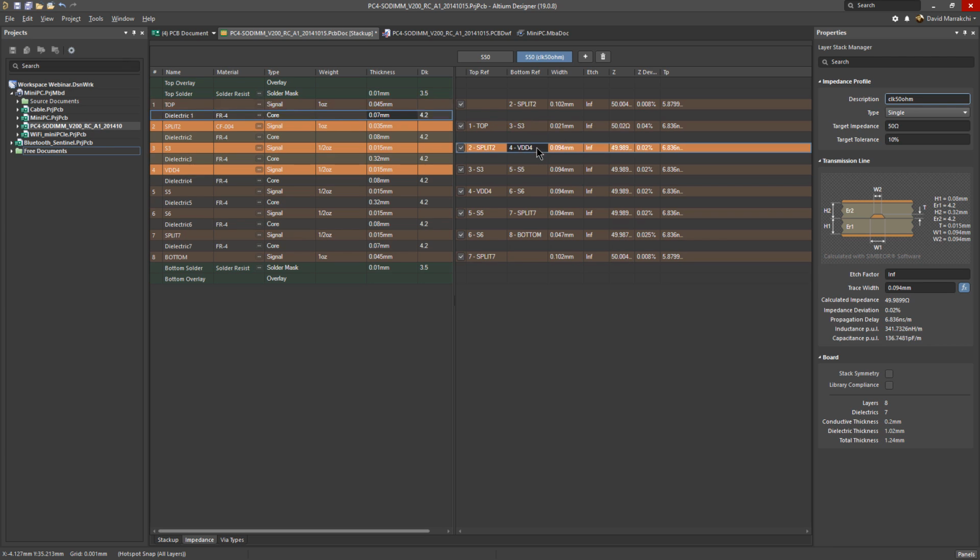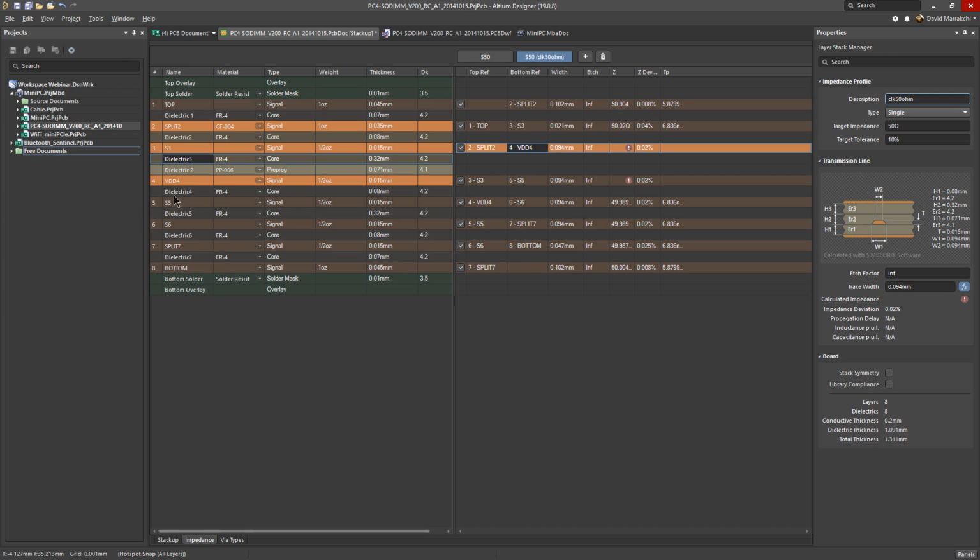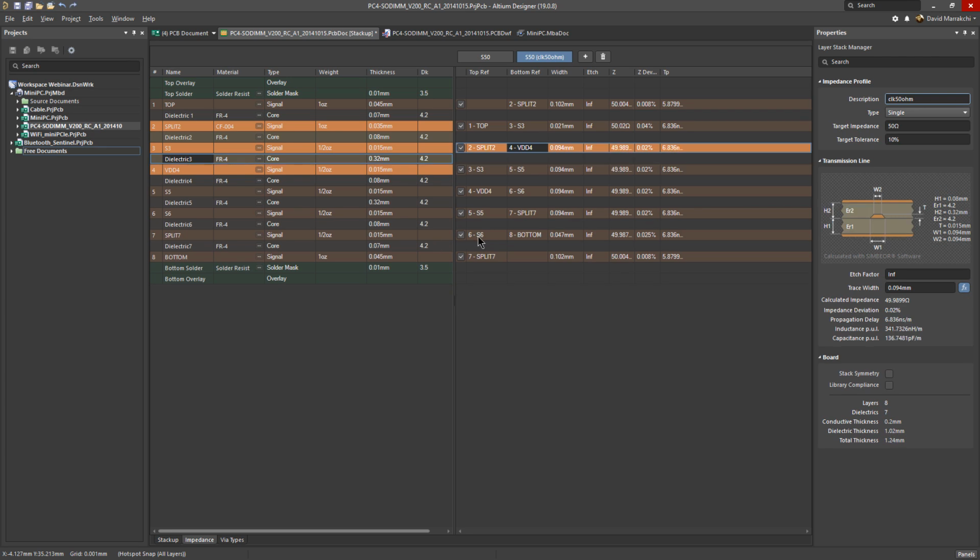One thing that is not supported yet, at least for this release, is if, for example, you have two dielectric layers between the signal layer and the reference. So for example, as soon as I added this additional layer, you can see here an error just popped up, and if I hover it says unsupported transmission line configuration. So just to keep that in mind. So let's remove it.